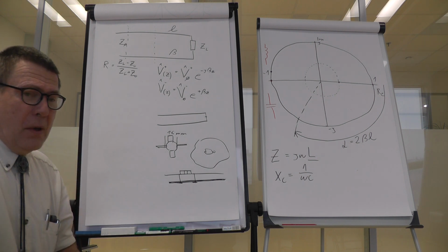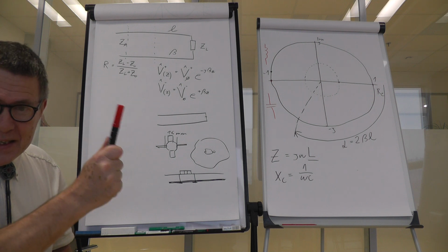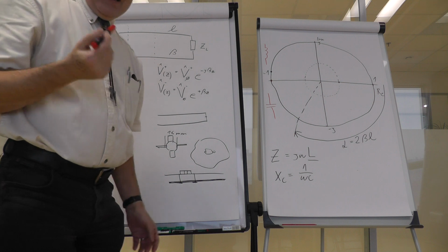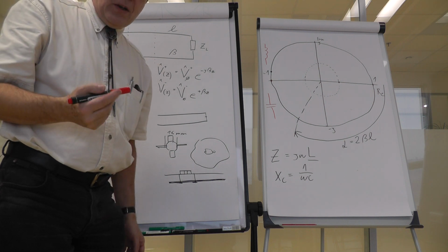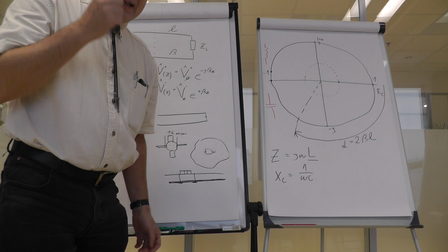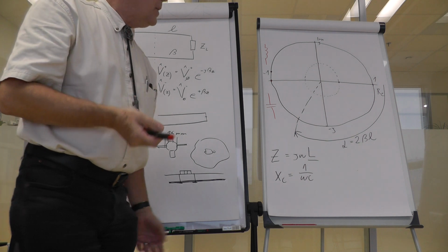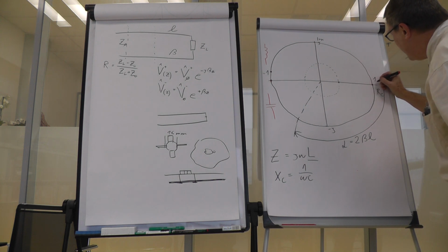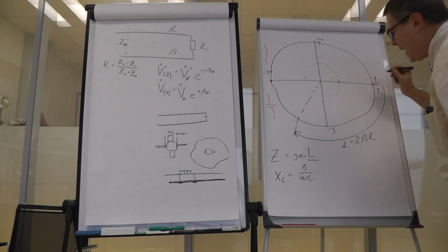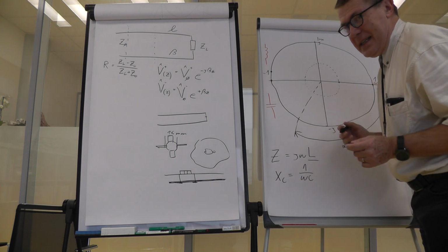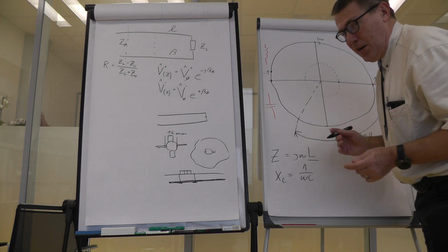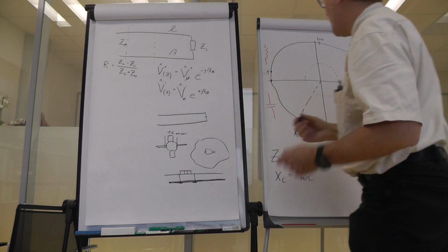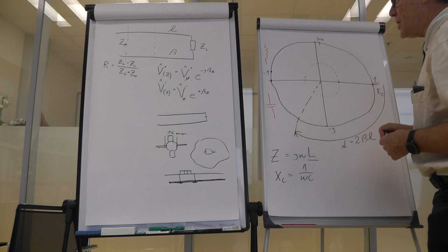I will start with impedances, and I will use a red pencil now. Which impedance causes a reflection of +1, exactly a real number 1? That's an open circuit. So this point, a reflection of +1, is caused by a load impedance which is infinity. Now, which reflection is caused by a short?